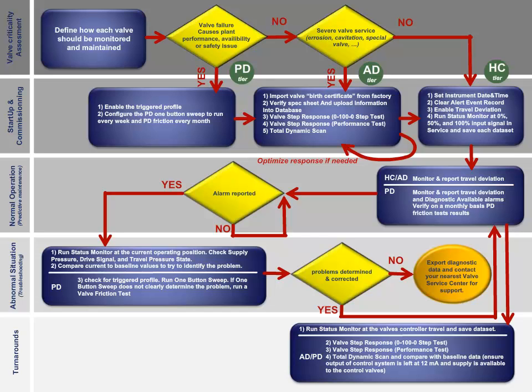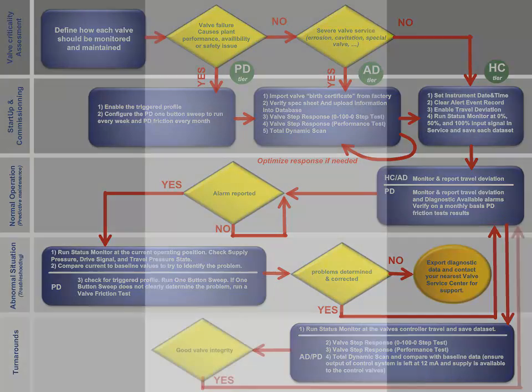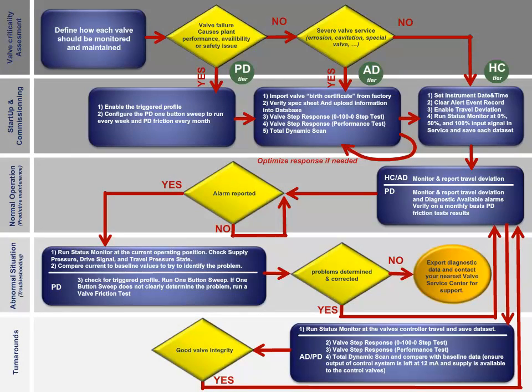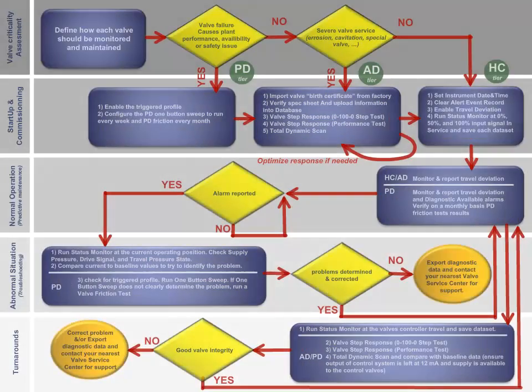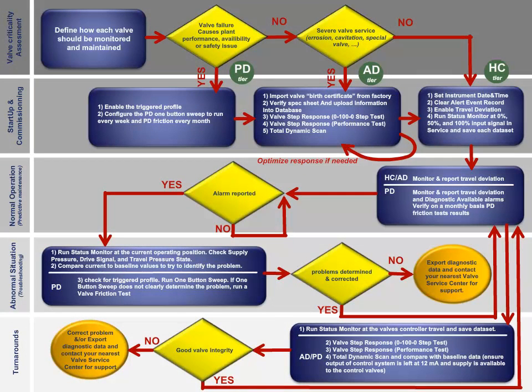Ensure output for control system is left at 12 milliamps and supply is available to the controlled valves. If integrity is good, then return to the monitoring phase. If not, then correct problem and/or export diagnostic data and contact your nearest valve service center for support.